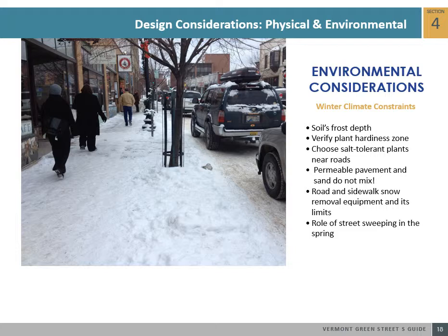In the winter climate, it's also important to understand the restrictions of road and sidewalk removal equipment. Adding medians or stormwater bump outs may require a different approach to snow plowing and in some cases require different snow plowing equipment. Municipal public works staff may need training to anticipate changes on roads with traffic bump outs, especially during winter months, to avoid damage to new curbing and to avoid storing snow in green stormwater infrastructure areas.